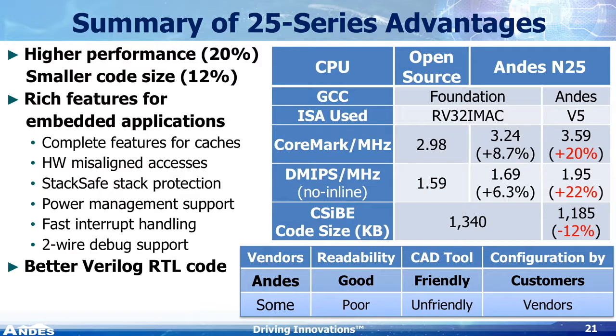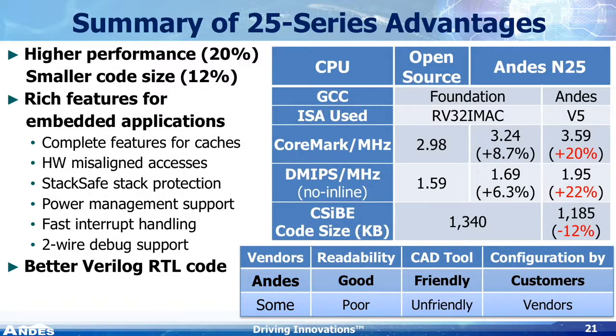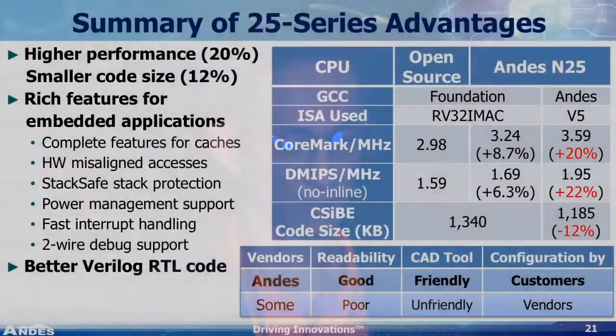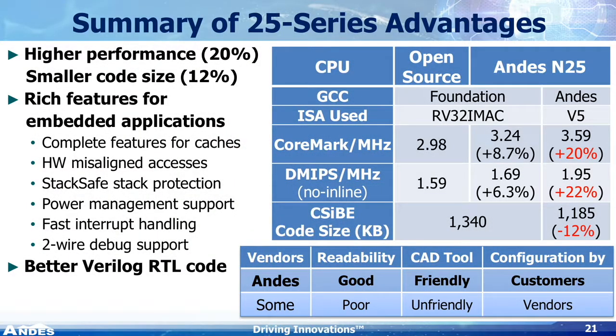Stack safe, stack protection, a very good feature, and also supported by our IDE for embedded software, can help you protect your stack from overflow or detect that for you. We have power management features, and we also already had the fast interrupt handling that we talked about earlier, but we want to make that a Foundation standard. For small, pin-limited chips, 2-wire debug support is very important. So we have that too.